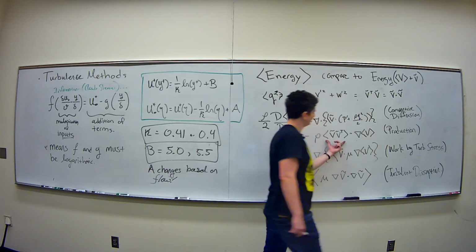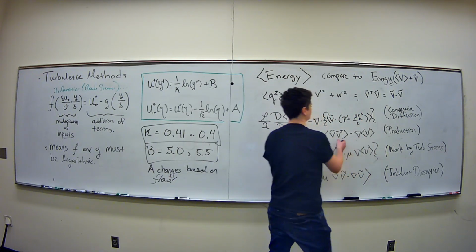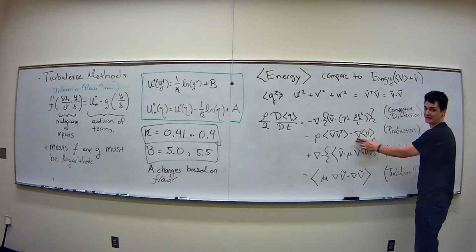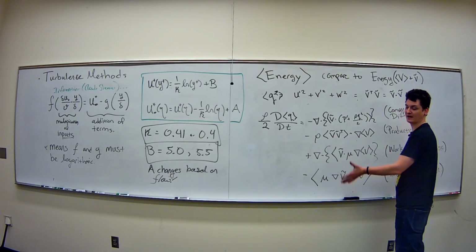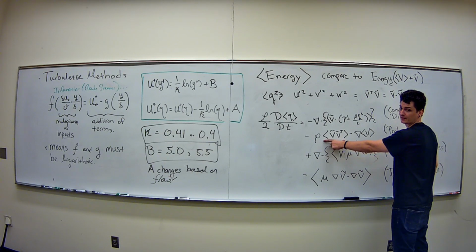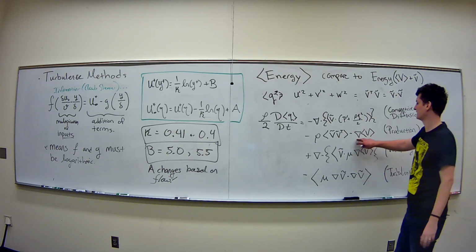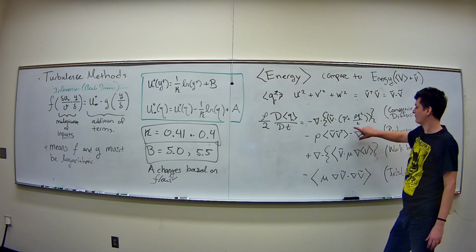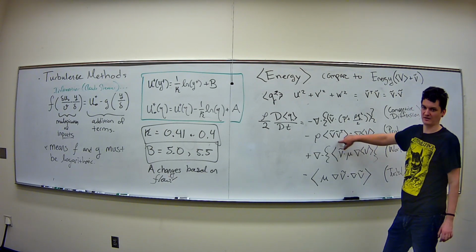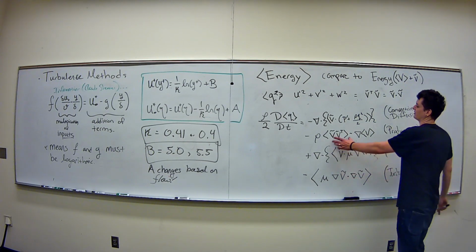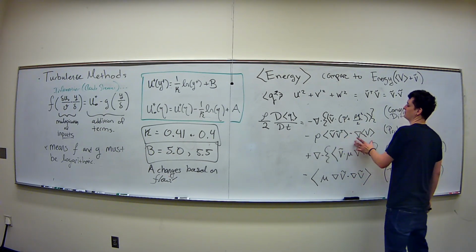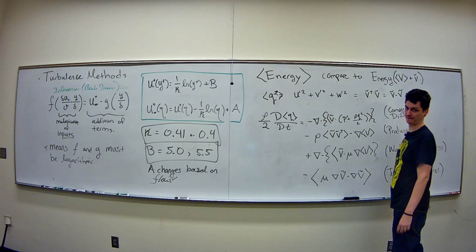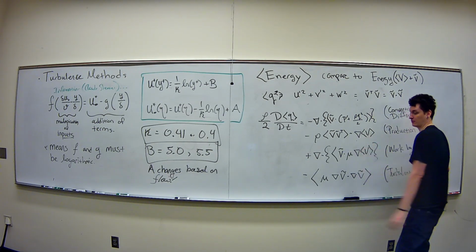The production term is this interaction between mean and fluctuations. So this is the mean strain rate tensor, and it's scaled up now by turbulent fluctuations. I'll say that again. The production term is the multiplication of my mean strain rate tensor scaled up by fluctuation properties. So there's an interaction now, how the mean flow interacts with the fluctuations to produce turbulent kinetic energy. Keep in mind this is a local term.